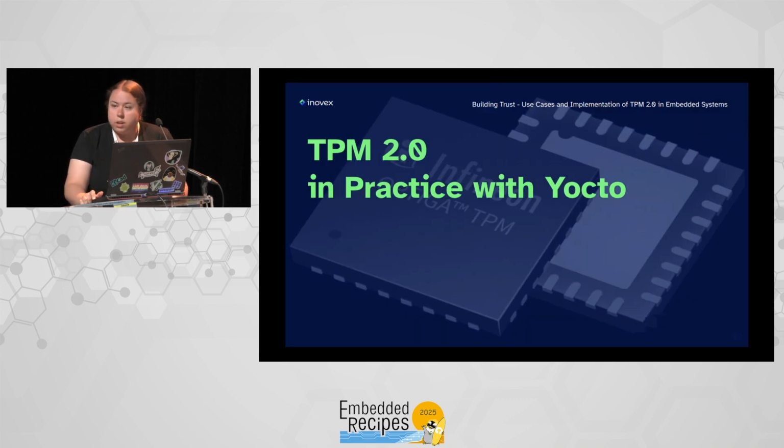And last, some practical examples from some use cases I implemented with Yocto. When you want to integrate a TPM with Yocto, there are basically 2 layers providing the TPM functionality, meta-security and meta-secure-core. Basically, both do the same. If I were asked, I would prefer the meta-security layer a bit. I think it's a bit better in quality and maintenance. But depending on your use case, you can also mix and match what is needed.